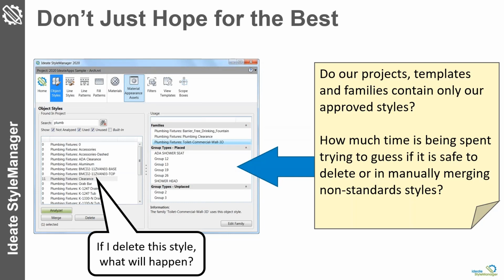So on lines within groups, so if the line is within the group, we can basically modify, or I should say isolate that information that is within the group, but we're not able to change, I guess, some of the information, depending on how Revit is creating that particular group. But there are some instances where you may have to isolate the group first and then open up the group editor and then be able to make those changes.